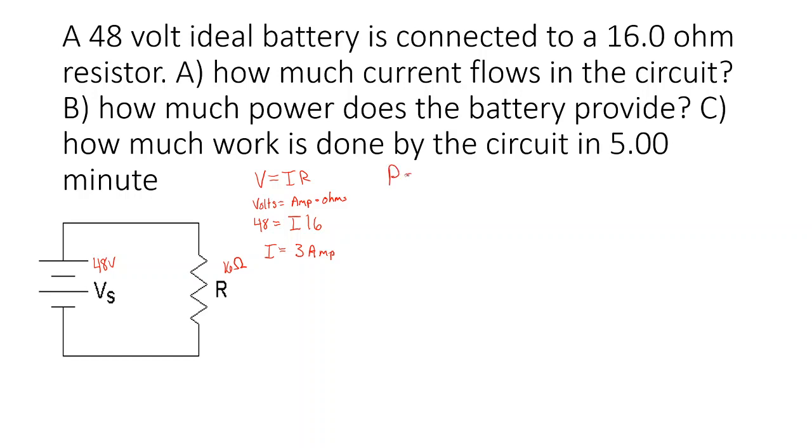So we can calculate power by the equation. We could say that it's I squared R. I believe maybe we talked about this yesterday, but the equation we had yesterday is that P equals V times I. And if V equals IR, we could substitute this volt into that volt, and if we combine that, we could get P equals I times R times I, which is I squared R. That's how we derive this second equation for power.